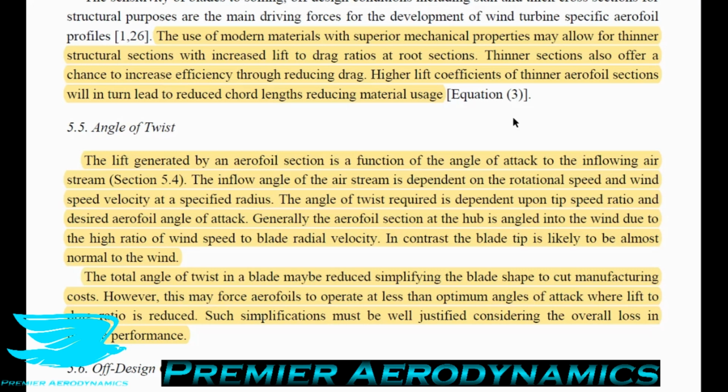So they say the total angle of twist in a blade may be reduced to simplify the blade shape to cut manufacturing costs, but this may force airfoils to operate at a less than optimal angle of attack, where lift to drag ratio is reduced. So simplifications, while they can be good in terms of manufacturing costs, will definitely reduce aerodynamic performance. It's better, if you can, to have each point along the blade twisted at the right angle to maximize the energy harvested on average.